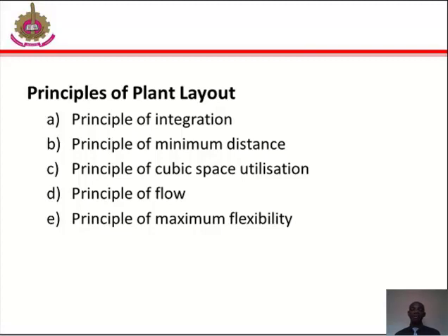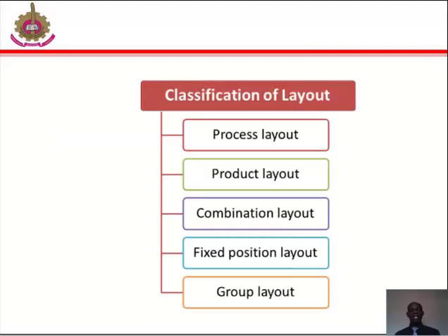Under principle of flow, a good layout is one that makes the materials move in a forward direction towards the completion stage. That is, there should not be any backtracking. And lastly, under principle of maximum flexibility, a good layout is one that can be altered without much cost and time. That is, future requirements should be taken into account while designing the present layout.